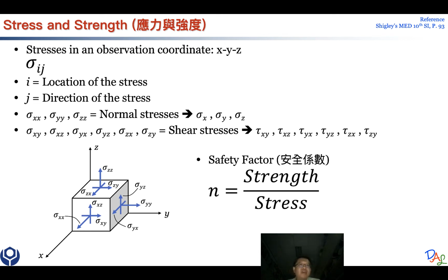There could be uncertainty in the material property or purity due to all kinds of reasons. You may expect some material to have some strength, but it actually is not as strong as you think. So with all those reasons, a safety factor with N equal to 1 could be dangerous.